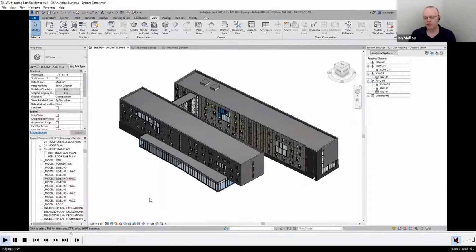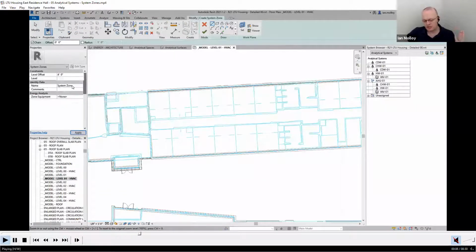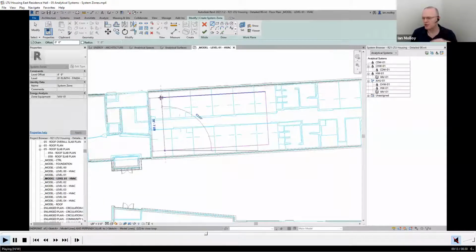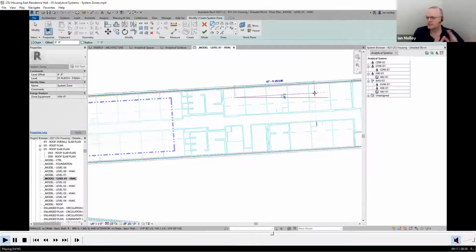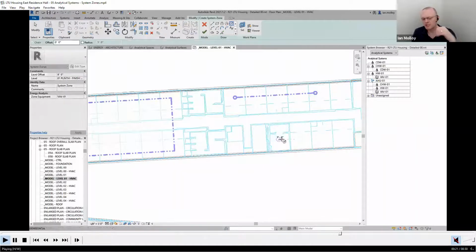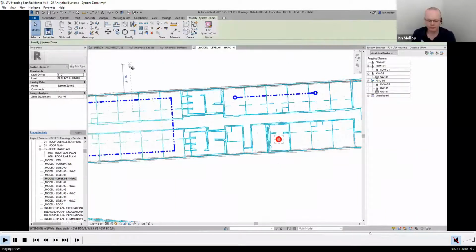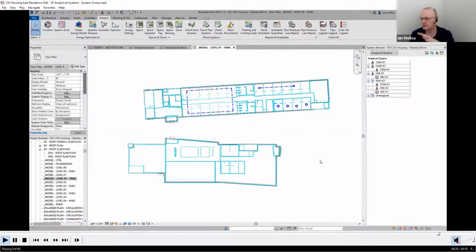And then once you do that, you can use this concept of what we call system zones, which is basically kind of like a BIM-based version of the kind of markup that an engineer typically does, and say, these regions are served by this air handler and or these sets of VAV boxes. I want one VAV box per space or that grouping on that space. So it's a way of capturing that design intent for a very specific system design, right?